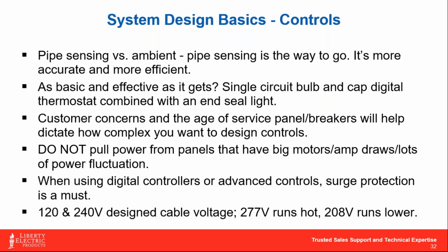Really when it comes down to it, there are also some factors within the facility itself that could be limiters, like the age of the panel that you're tapping for power. Do they make breakers for that panel anymore? Can you even get GFI breakers for it? Because in a lot of these cases where you can't get an upgraded GFI breaker, now's the time to consider using the control that has GFI integration in it.